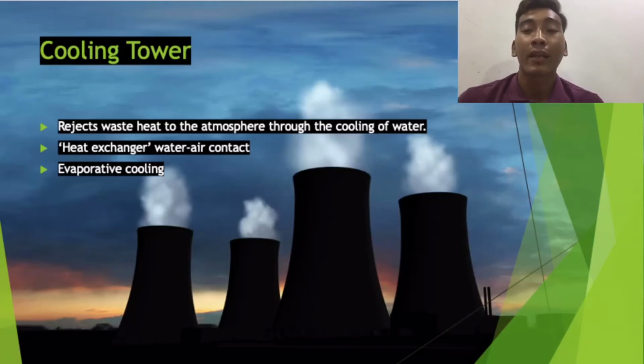The water then gets distributed by cooling tower nozzles to the wet deck. At the same time, air is drawn through the air inlet louvers, forcing water to evaporate. Evaporation causes the heat to be removed from the water. The hot air naturally rises out of the tower.